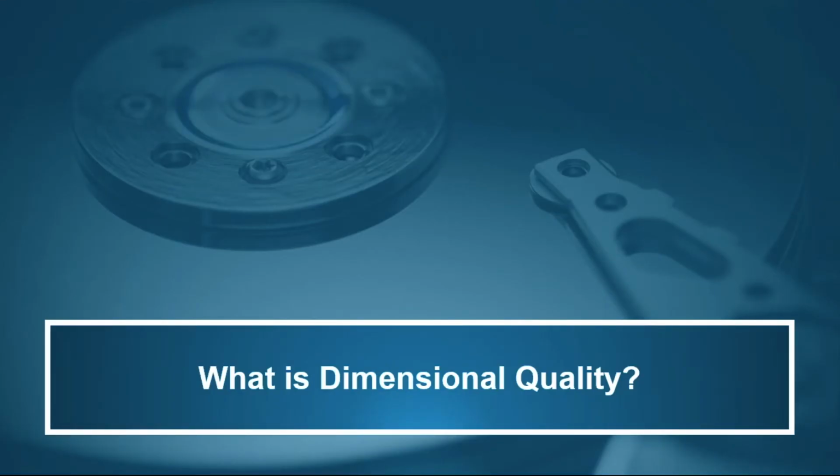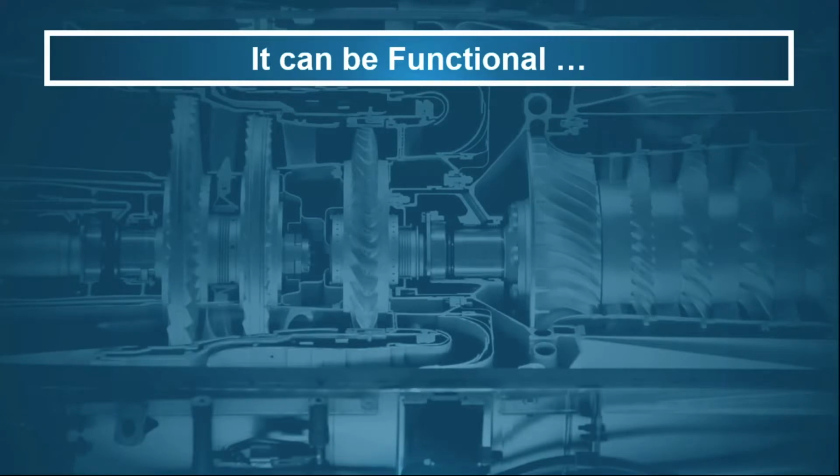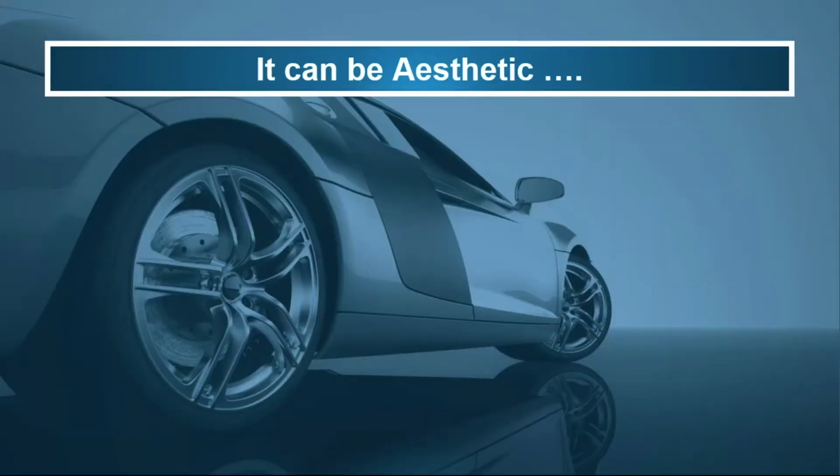What we're going to talk about specifically here is dimensional engineering and dimensional quality, not just quality, but dimensional quality. So it could be functional. This happens to be a jet engine, but as we go around here, the clearances around these things, we don't ever want them to touch, but we want them small so they can create pressure going through there. So it's a functional requirement, but there are dimensional requirements that have to be met, and the quality of the engine is dependent on these dimensions. Similar to that phone, some of the dimensions and the way things were made meant it did not function properly.